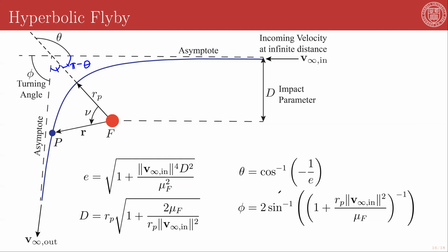The reason why we're making such a point of stating what we can parameterize these equations with is because these are design tools. And so we need a fixed number of inputs in order to iterate over possible designs. The periapse radius is a really good input because it allows you to set a minimum separation during the flyby between your spacecraft and the body it is using to perform the gravitational assist.